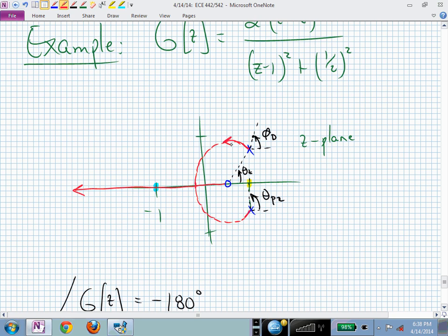These are taking off at those respective angles. They meet right here. Could you find the gain that would get you to this point? After they reach that place and hit each other, they split off. They live on the real line. One goes to that zero at 1/2. The other one goes off to minus infinity.